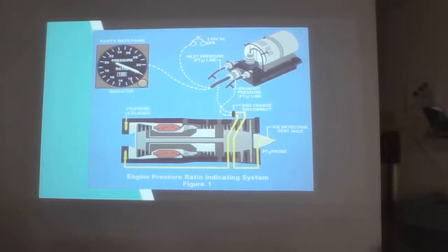And it says here 6 places. So it's going to vary by engine how many probes are on this PT7 probe. In this diagram, it's saying that it has 6 probes. So it's taking a temperature in 6 equally spaced areas at the exhaust of that engine. And then here's your wiring for all of those readings.